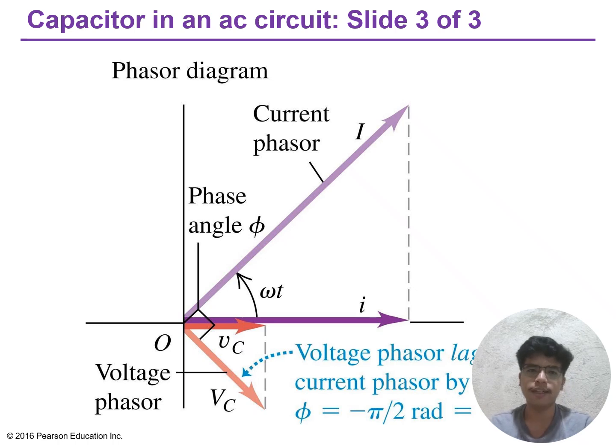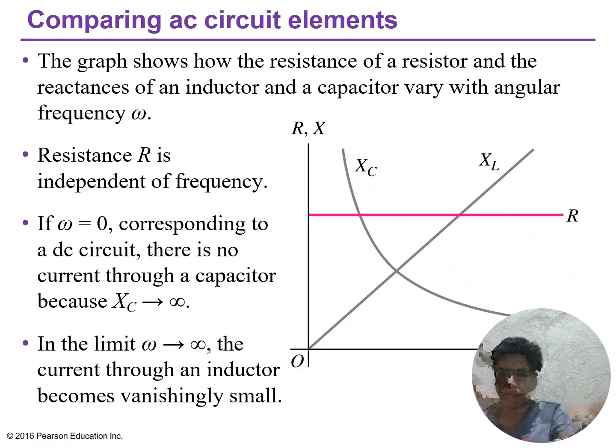For circuit designers, the capacitor's current leading behavior is valuable. Capacitors can be used to correct the excessive current lagging behavior caused by inductors, a technique called power factor correction, used throughout industrial electrical systems. The consistent 90-degree separation between current and voltage for capacitors, like the same relationship for inductors, provides a stable reference point for circuit analysis regardless of the operating frequency.